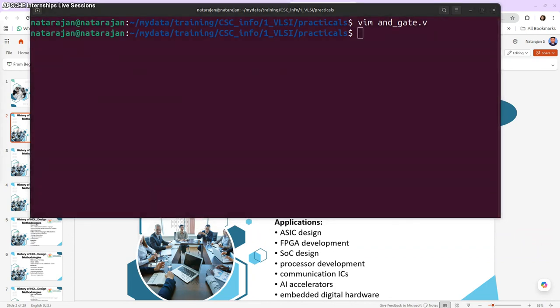Now the question comes, how do I simulate? How do I compile it? iverilog is the command, with the gate file, and let me have an output of simulation.out.